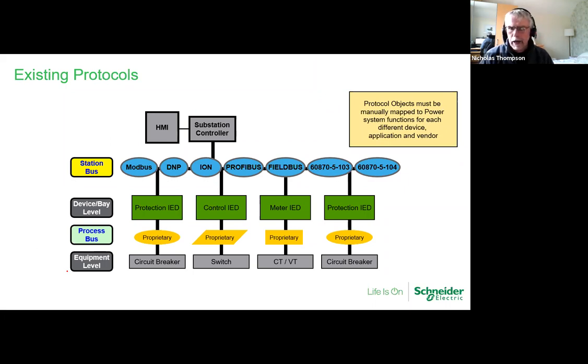Now, if you take a traditional large substation and you've got comms on there, the traditional route is to choose what protocol you want, and then you select what supplier you want, and it might be multiple suppliers of meters, relays, etc. Getting all those to work together can be very, very time consuming, and this is where IEC 61850 comes in. So if you picture that in your mind, you've got a choice of your protocol and you've got a choice of devices, and getting two different manufacturers' devices to talk to one another can be the most problematic thing on earth. Nailing fog might be easier.